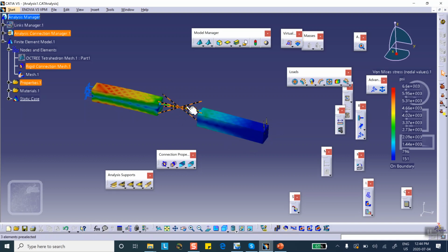And this middle portion is rigid, so presumably there's no deformation in it, no stresses in it. Now, this patchiness, you know what it is for. It's because the mesh is not good for the purpose that we have in mind. You can make it smaller, or you can go to parabolic, but that is not the purpose of this particular presentation. So let me deactivate this plot.